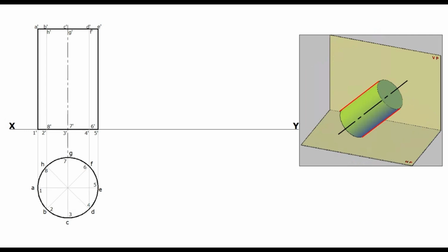In the second stage elevation, draw a 45 degree inclined line. This line is the vertical side of the rectangle of the first stage elevation. Based on this 45 degree inclined line, reconstruct the rectangle. Mark the top base points and the bottom base points.